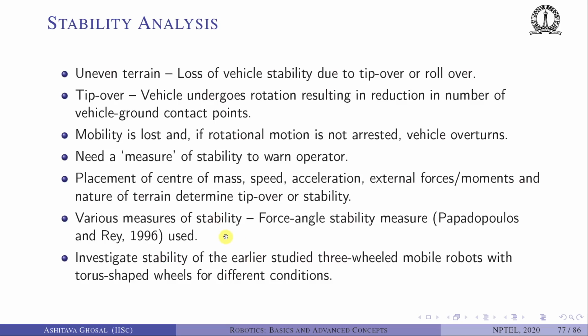There are various measures of stability which have been developed. We are going to use something called the force angle stability measure. This was first developed in '96. And we will investigate the stability of the previously developed three-wheeled mobile robot with torus-shaped wheels for different conditions.